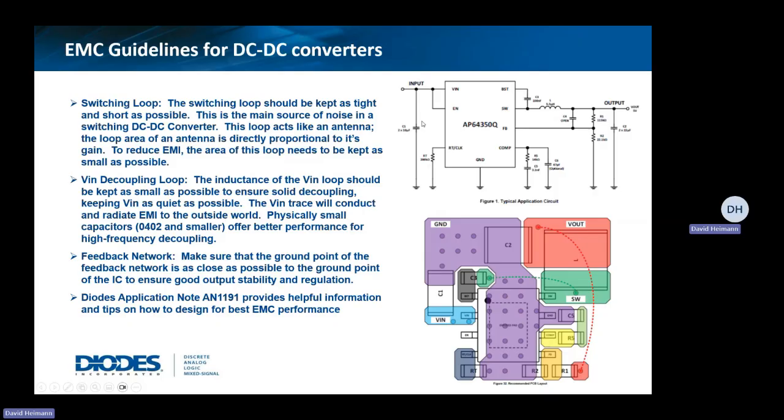We don't show it in our reference schematic, but it's good practice to put a small case size capacitor, potentially a lower value, close to this VIN capacitor as well, to decouple or shunt the high frequency noise directly to ground, because you're going to have better performance with a smaller case size.